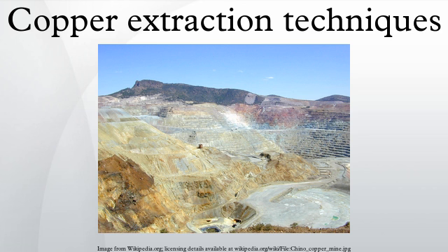The slag and the matte form distinct layers that can be removed from the furnace as separate streams. The slag layer is periodically allowed to flow through a hole in the wall of the furnace above the height of the matte layer. The matte is removed by draining it through a hole into ladles to be carried by crane to the converters. This draining process is known as tapping the furnace.